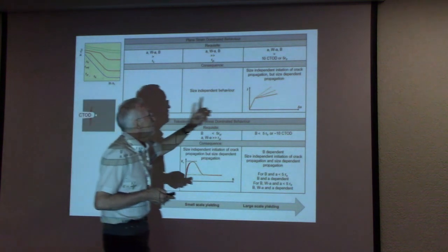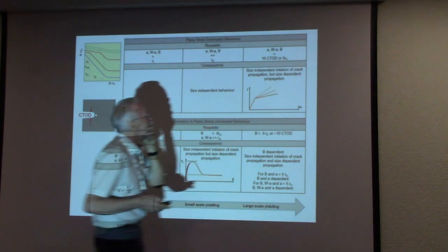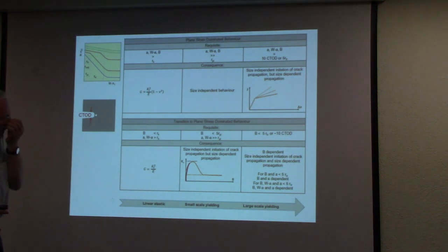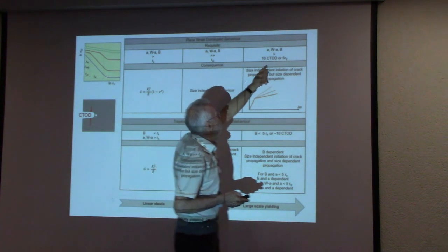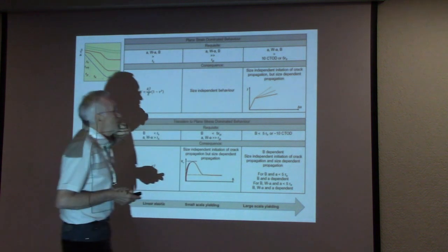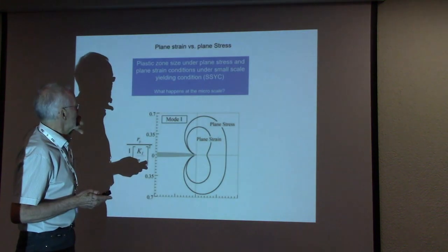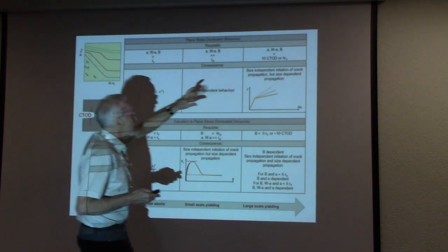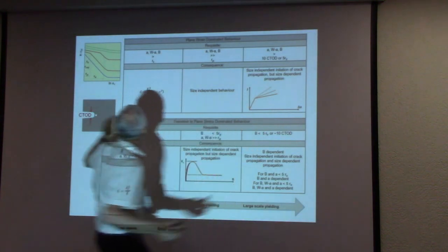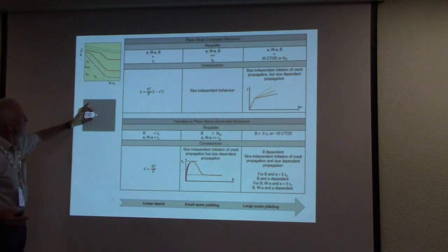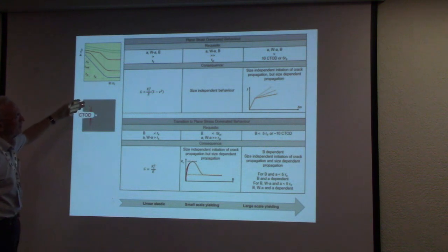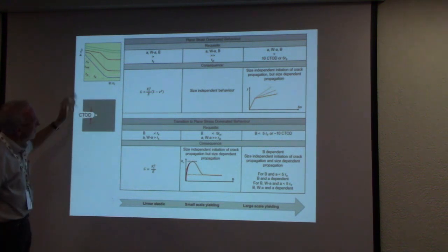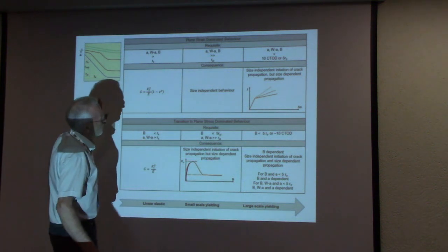And when we go now to elasto-plastic fracture mechanics, what we know from elasto-plastic fracture mechanics, where the crack tip opening displacement is significantly smaller than the thickness, in the old standard it was about 25 times CTOD, now in the new one it is 10, but 10 is really a bit tricky.